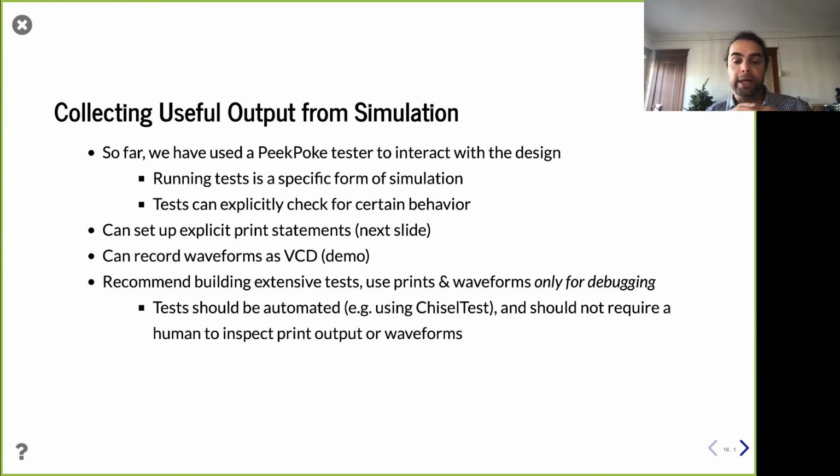And so when you're simulating, you have a few choices, right? When you're using a test bench, like you just were, you can manually set the inputs and manually check the outputs. However, if you're just simulating in general, especially outside of a test, you may also want to do other things, right? You may want to, for example, print things. Printing at first might seem like a very weird thing to do, because wait a second, what does a print mean in hardware? Well, guess what? There is no print in the hardware, right? The hardware is the hardware blocks instantiated, but if you're talking about simulation only, yes, you can set up your simulation such that there's a print statement that happens under certain conditions, and you can print out values and look at them.